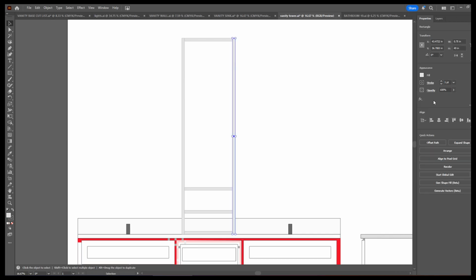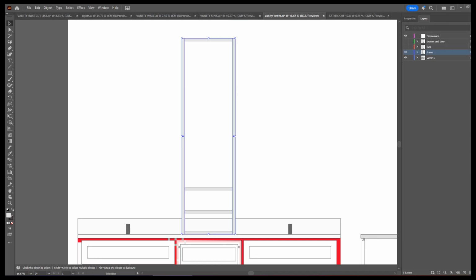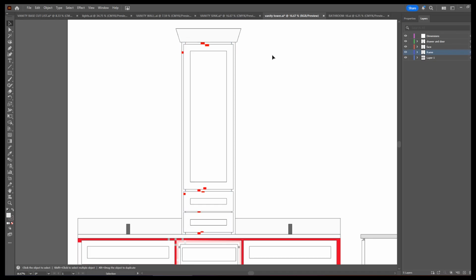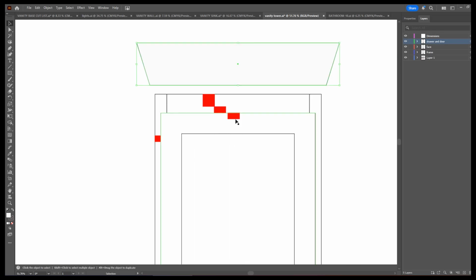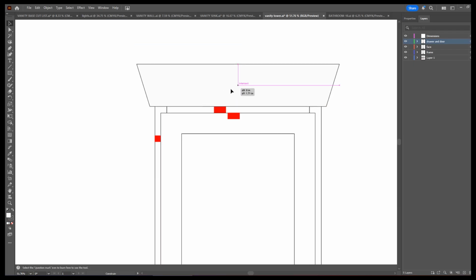It's going to be right at 49 inches tall, 14 inches wide, and then something else. I threw this box up here that's representative of trim across the top. If I move that out of the way, you can see that I've got a 1/2 inch overlap between the door and the piece of face framing, and then I've got a 1/2 inch gap between the top of the door and whatever piece of trim I'm going to put up there.